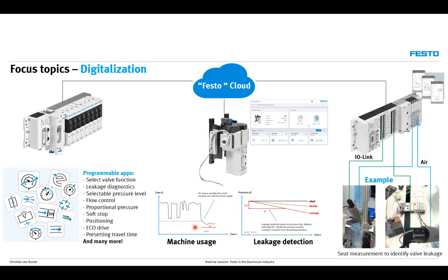Last but not least, and this is more on the valve terminal technology, where we also make use of the dashboards, is an example where we have an angle seat valve where we use a proximity switch at the rear side of the valve to read the status of the valve seating. We were able to detect an opening difference of 0.01 millimeters. For this process, where it absolutely was required that the valve was fully closed, we could detect the status of the valve.